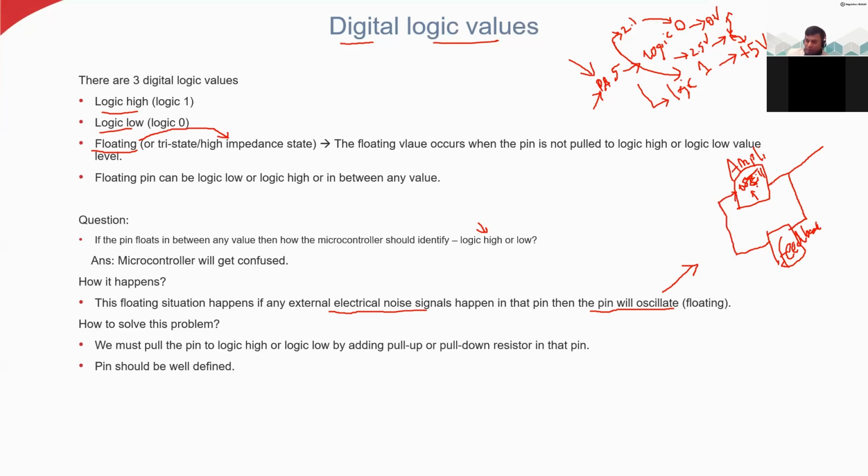So here we have the thermal noise, which will be developed to a certain level. This is the gain of the amplifier, A, and beta is the gain of the feedback stage. So A and beta together is called the loop gain. This is a closed loop. And the oscillation condition is the Barkhausen criterion. That is the condition for oscillation, the Barkhausen criterion.